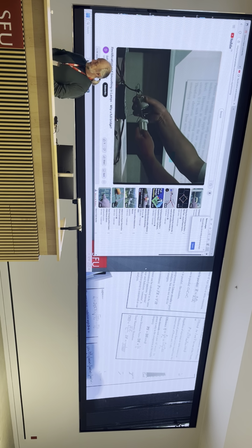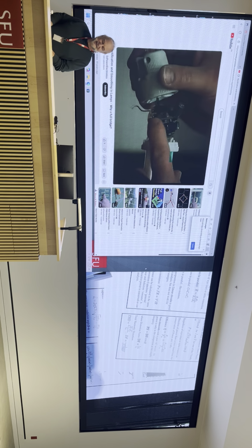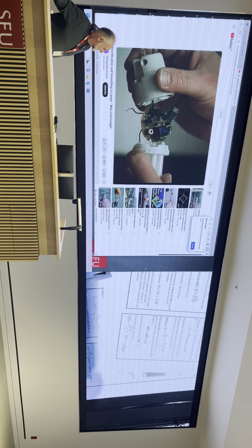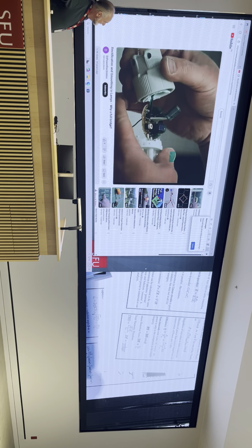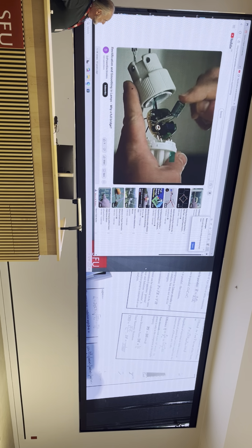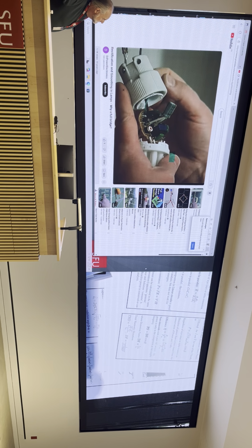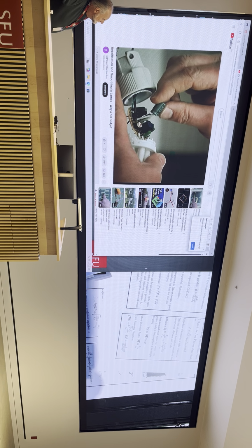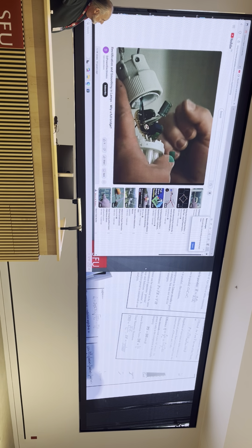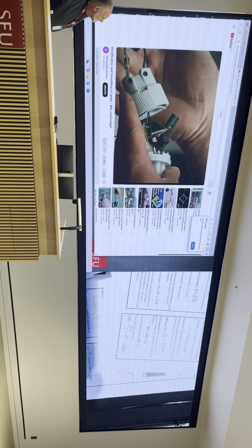Taken to pieces, you can see in here there's about 8 diodes, actually 4 of which are the full bridge rectifier, and then we have the smoothing capacitor. So it's a bit old, so I apologise for that. That happens to be, in this case, 2.8 microfarads, 400 volts, coming straight in off the mains electricity.